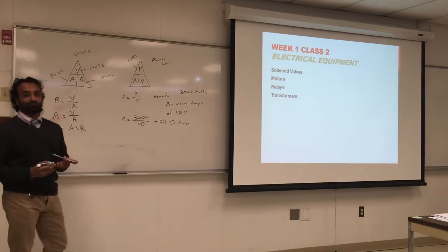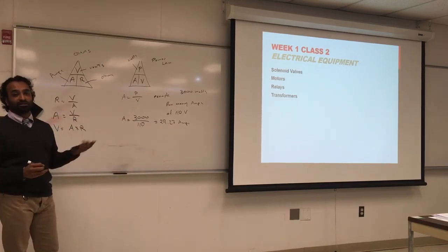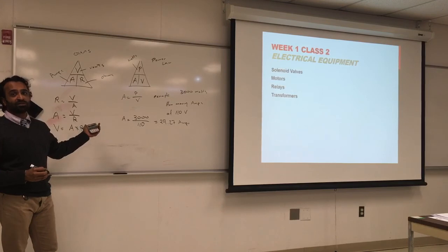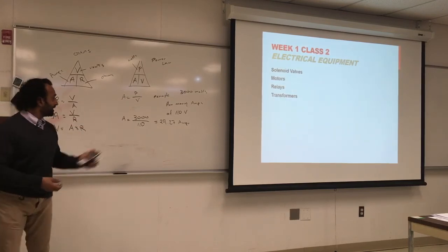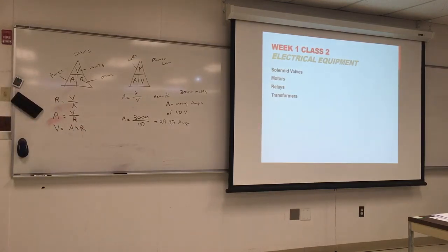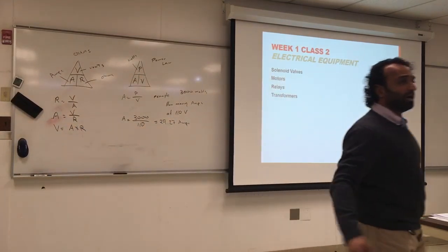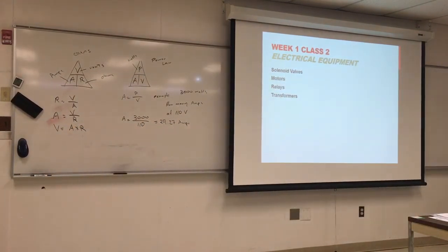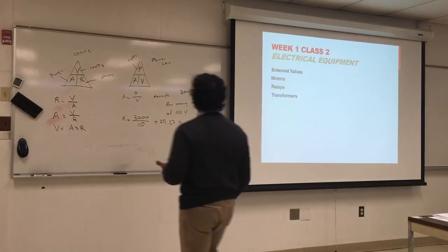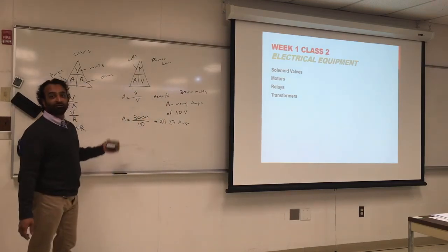Is that acceptable? No. If you're going to have equipment that draws this much, it will have its own circuit breaker, and probably you're going to go with 30 amps. And we do have some of those. We have 20 here, this is 50 amps, and it's 100 amps. So you've got to get a circuit breaker especially for that equipment and put it in the control panel. Examples are the clothes dryer, washer, some dishwashers, and an industrial size microwave, which will probably have its own circuit breaker.